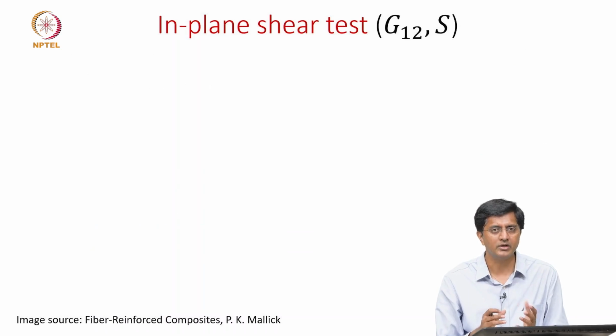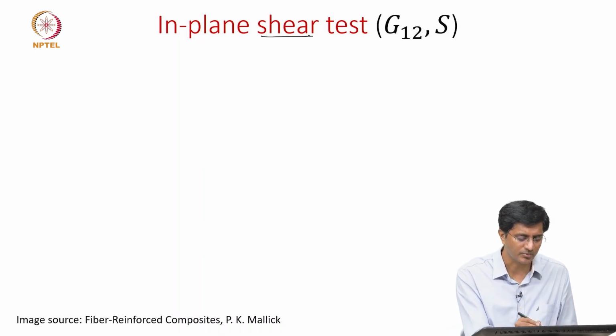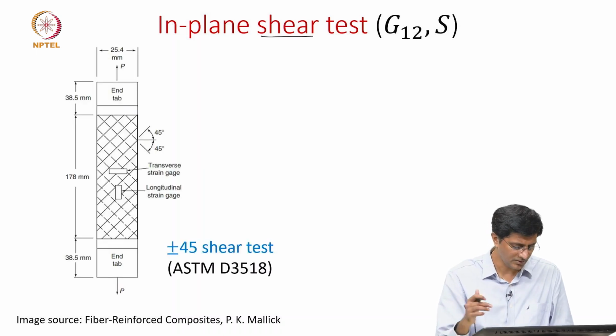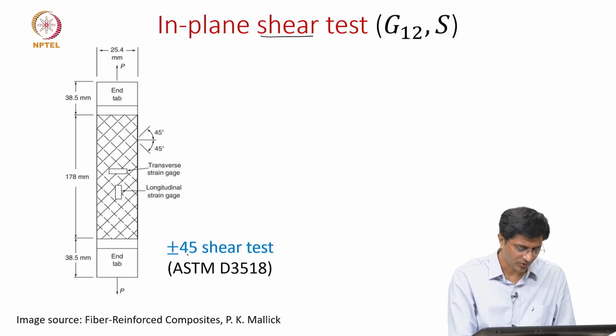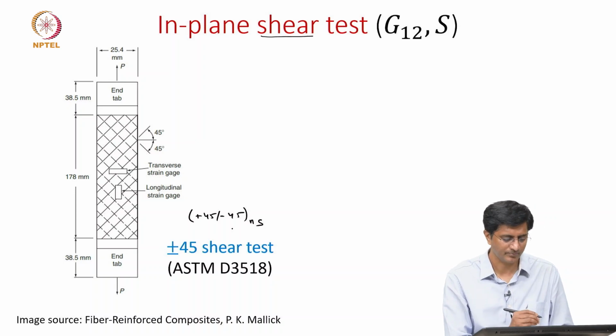Until now, we have been focusing on the tension, compression, and the flexural test, which are the in-plane properties, but the normal stresses we are looking at. Now we will look at the shear stresses applied. How do we apply shear stresses in plane? So one method is to use this plus minus 45 shear test, where we have a laminate in this form, like plus 45 minus 45, maybe we can repeat it n times and ensure that it is symmetric.